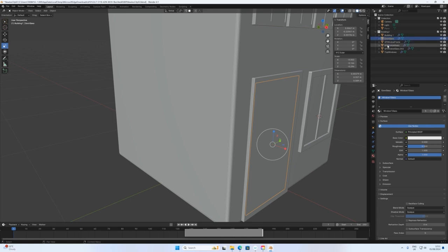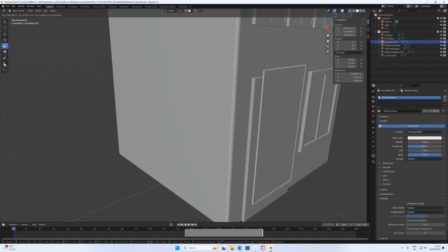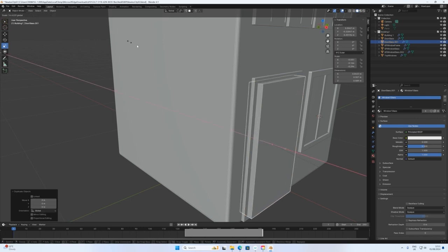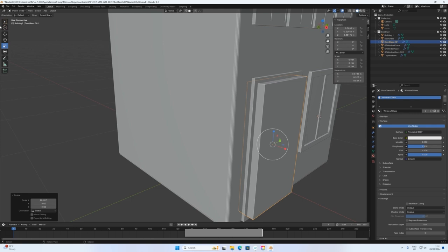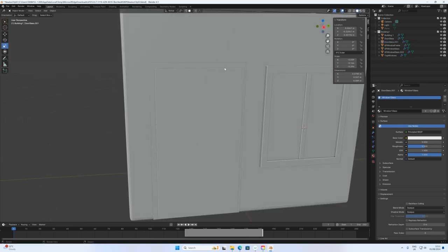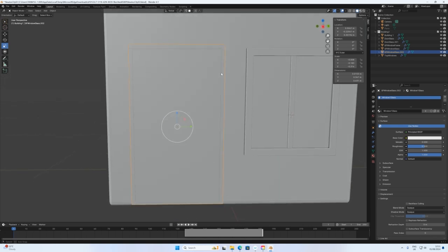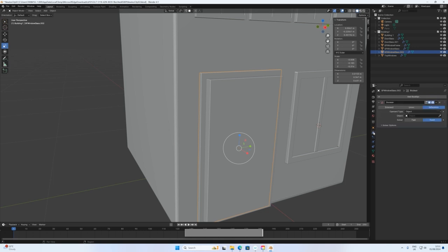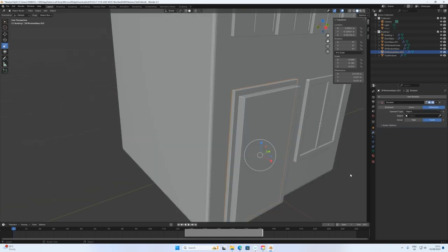The door glass. Okay. And I'm going to duplicate that, but to create the cutter, duplicate, Shift D, sorry, escape, and then scale in X, and do the same thing that you did for the window. Add a boolean, select that, add a boolean.